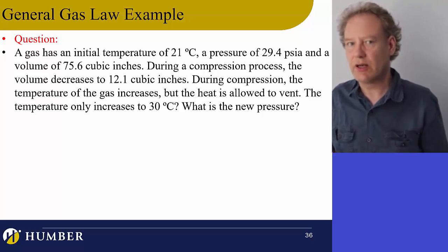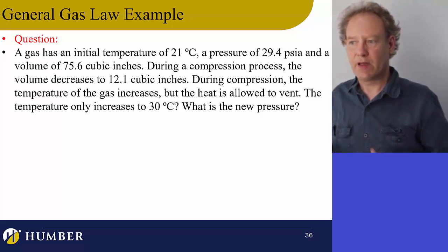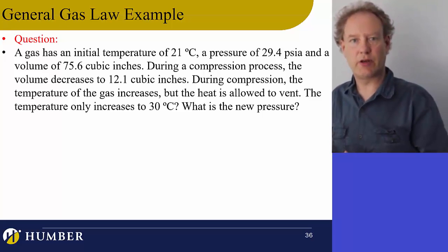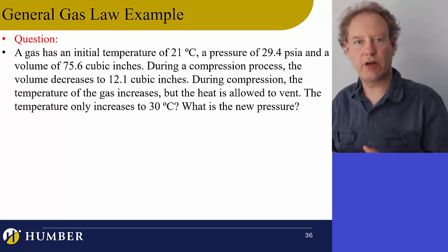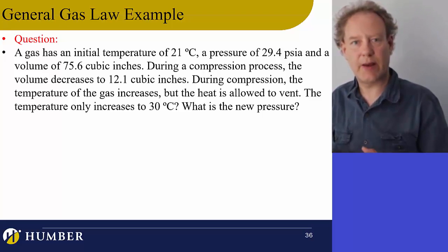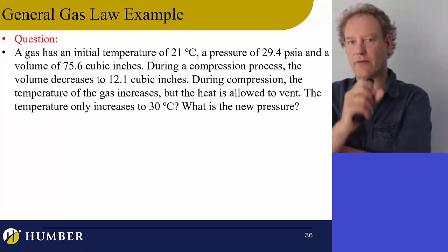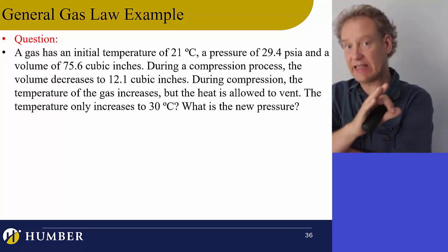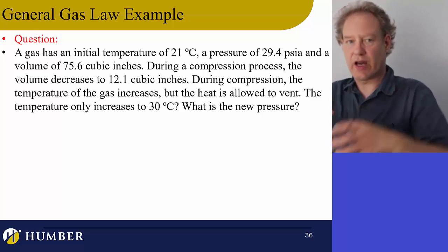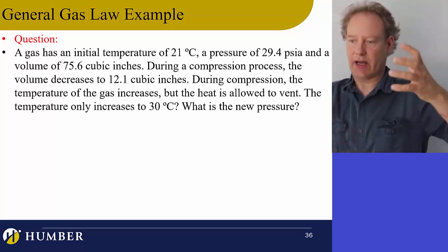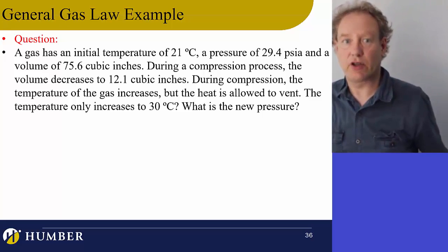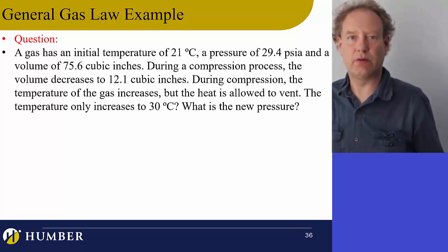So what's the issue? Well, the issue is that heat dissipates. So that gas will lose its temperature. And if the gas loses its temperature, it will affect its pressure, because temperature and pressure are linked. So if we take the gas out of our compressor and we don't let the heat leave, that heat ends up in the tank. Now we've got a pressurized gas in a tank, and it's hot. Well, if I just let it sit there, it's going to cool down. Well, the pressure will decrease.